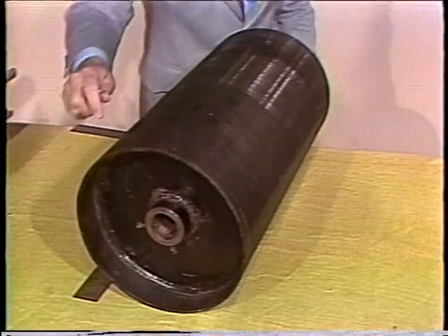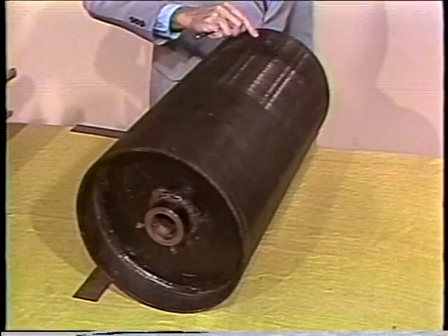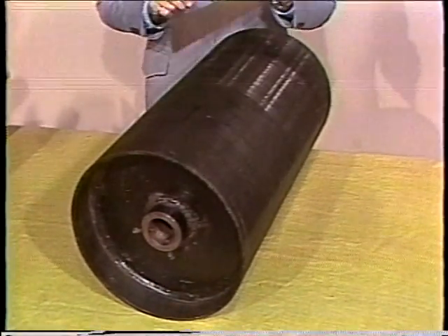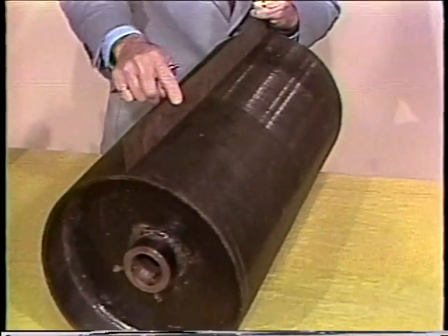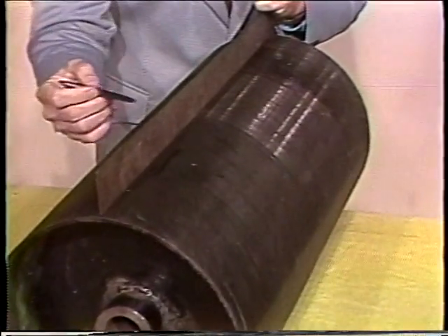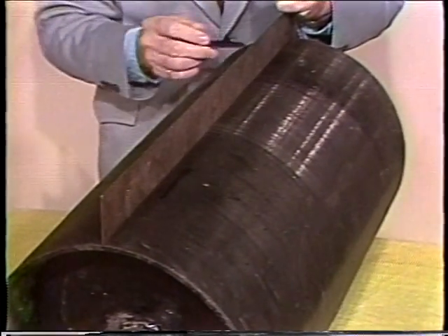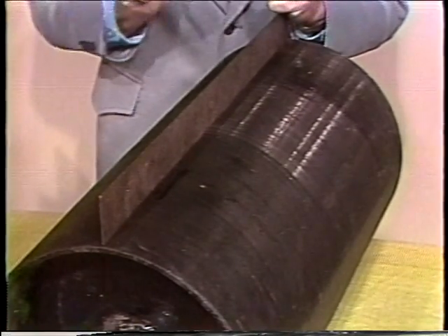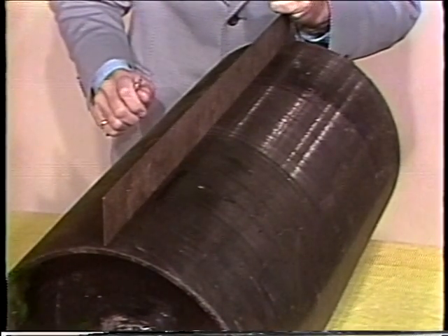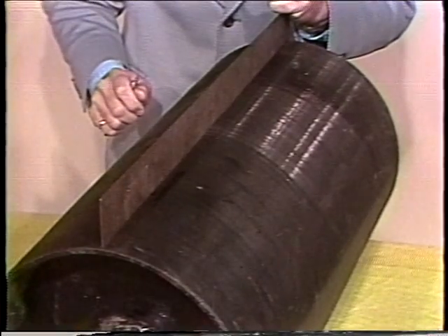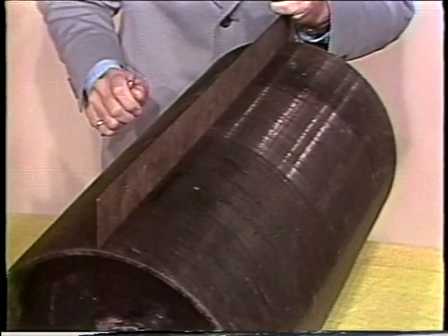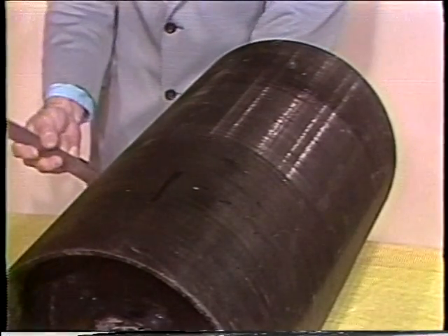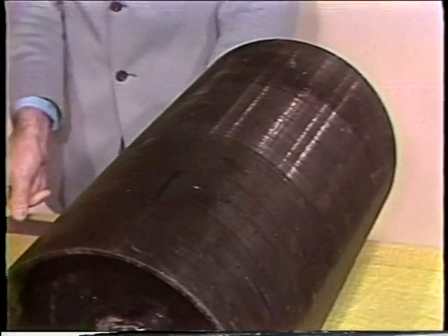The pulley may be flat, which means it is flat across the surface, or it may be what is known as crowned. This means there's a slight taper from the center, here, to each end. Normally, it's tapered 1/32 of an inch to 1/8 inch per foot of width, depending on the manufacturer. This taper or crown helps to keep the belt in the center of the pulley.